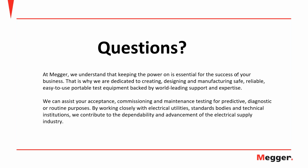Absolutely, a very good point, James. And because of that, IEEE no longer recognizes D877 as a valid breakdown test for oil that comes out of an operating transformer. It's still okay if you're sampling from a bulk container, or from an oil circuit breaker or a regulator, something like that. But for transformers, the 1816 method is considered to better simulate the conditions inside an operating transformer, and so it's the recommended test now.